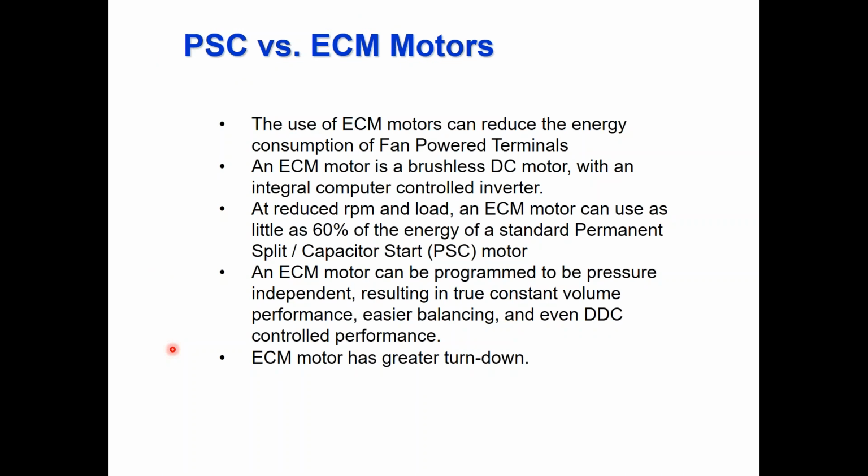In each of these series or parallel boxes, you can have ECM motors or PSC motors. I think you guys are pretty familiar with that technology nowadays anyway, from other walks in life, and furnaces and fan coils and all that kind of stuff. ECM motors, generally speaking, are more efficient, and they typically have more different operating points that we can operate them at in a more easy to control fashion.